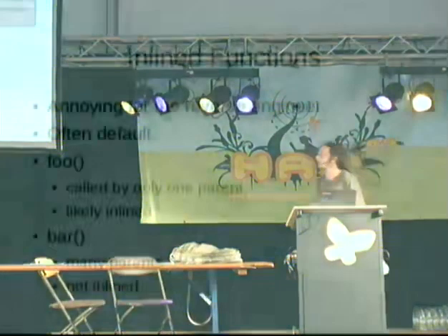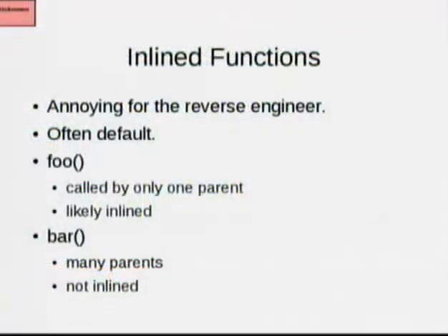You also have to worry about function inlining, because on these platforms, having such little RAM and such little stack space, it's more efficient to inline a function and save that call on the stack, even if you have enough flash memory to hold it. Because the code executes from flash memory, it does not execute from RAM.